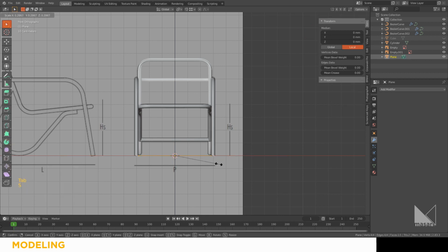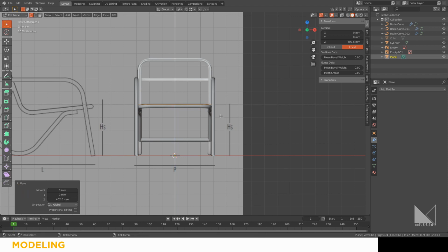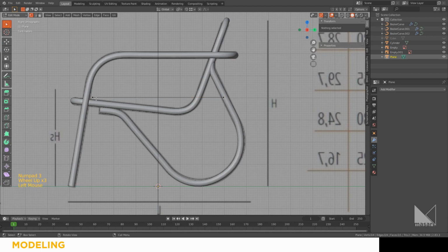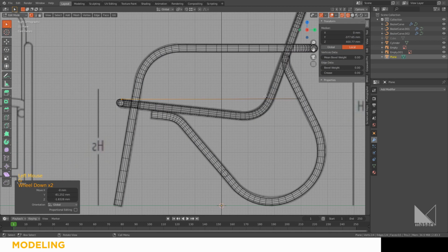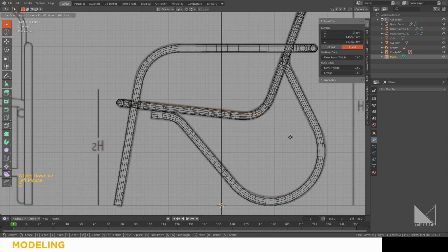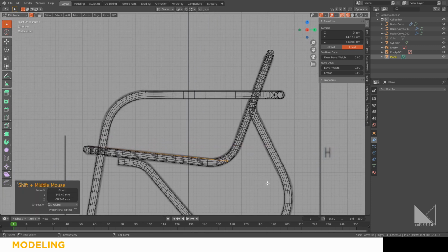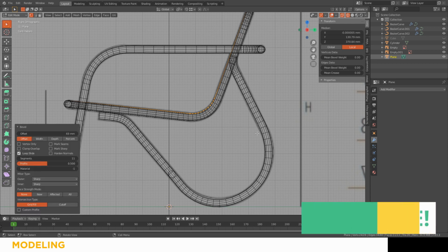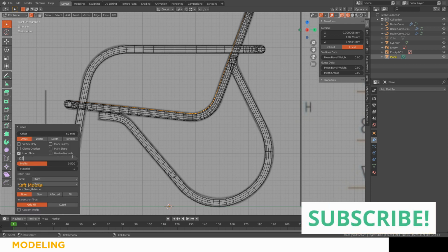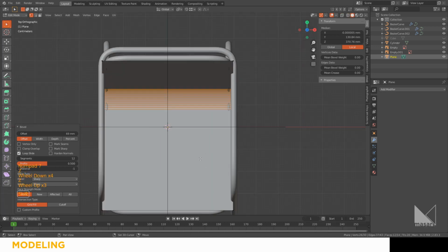I'm gonna scale it down and pull it up right here to the side view, and you can see you should put this one to this and put this one to maybe this side. Gonna extrude again, and then for the one you can control B to bevel it and increase the resolution, like 12 to be even.